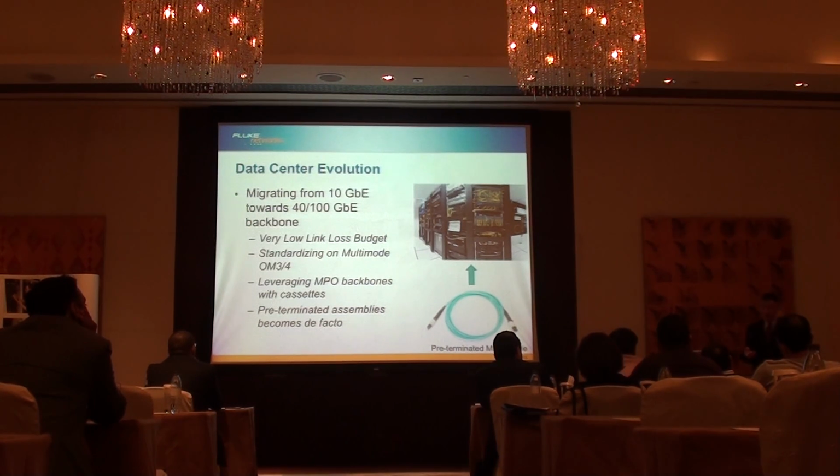So in order to take care of that, what they did was they increased the index of refraction of the core of the fiber, so the middle mode or the lower order mode will go slower, and then the next grade would have a little bit higher index of refraction, higher and higher. So when you transmit the signal in a multi-graded index fiber optic cable, all the signal gets across at the same time.